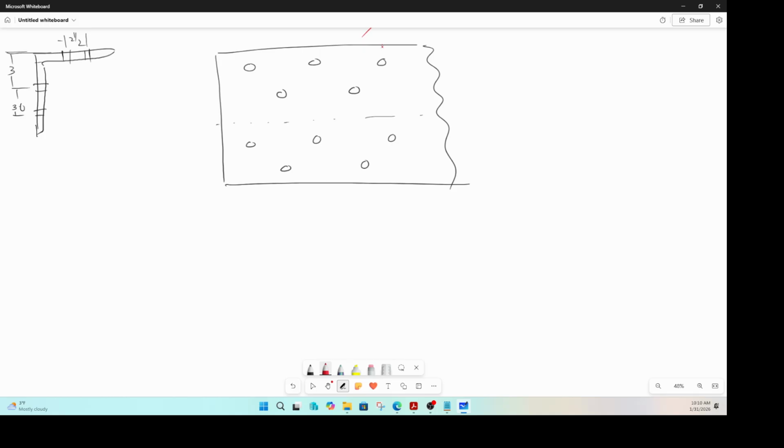So the failure can happen along this plane, right? Or it can happen along this plane like that, right? So we need to calculate different net areas and calculate the least A_n. And when you unfold this, there is also a certain rule as to how you calculate.